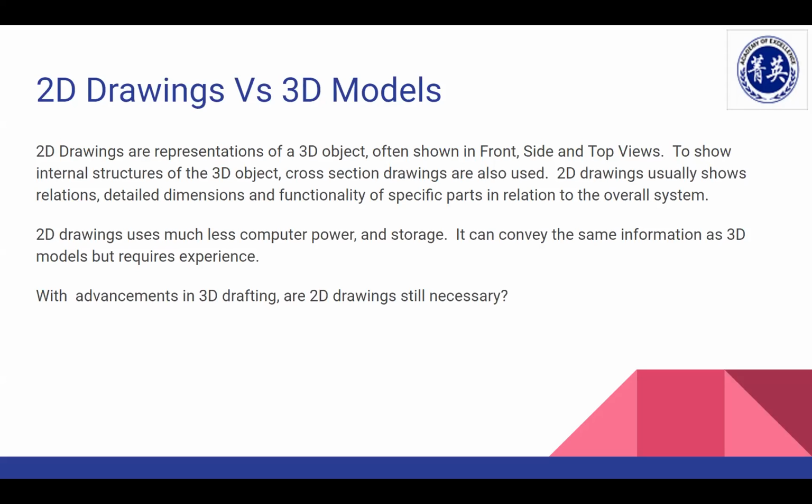So in the 3D drawing, sometimes, depending on what phase you're looking at, it's difficult to see what the dimensions are, right? So drawings are necessary to start out with not just for the designer to know what it looks like, it's also for the people that make the parts down the road. So they have to know exactly how long a certain line is, how big a certain hole is. And a 3D drawing sometimes gets really busy really fast. And since there are parts covering each other in the 3D view, oftentimes it is still necessary to use a 2D drawing to show the exact dimension of everything you have designed.